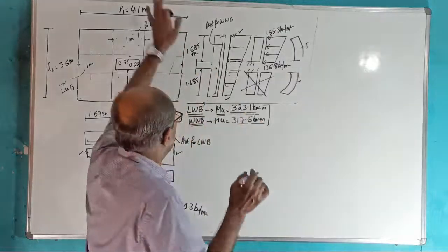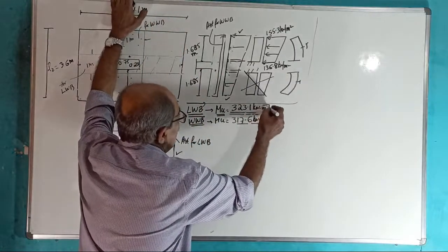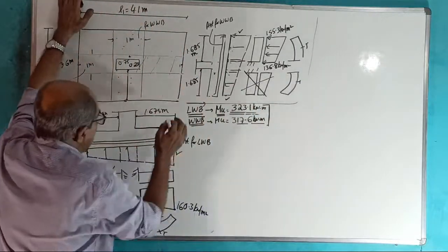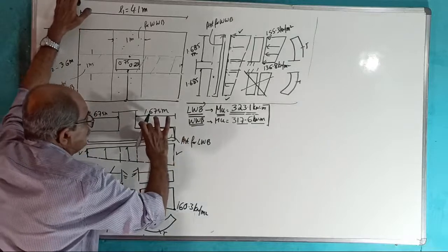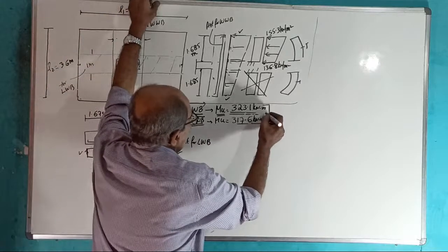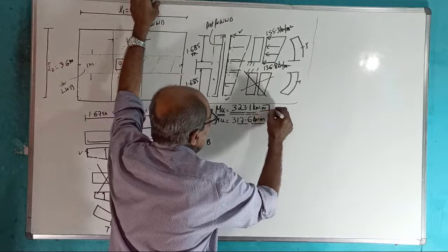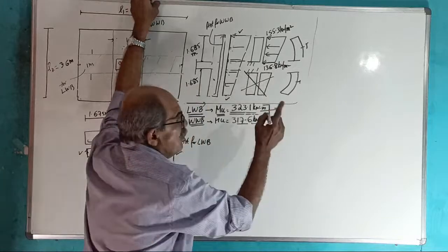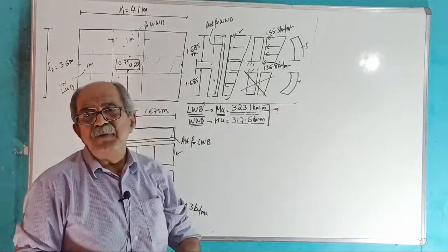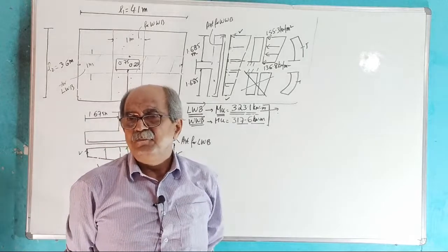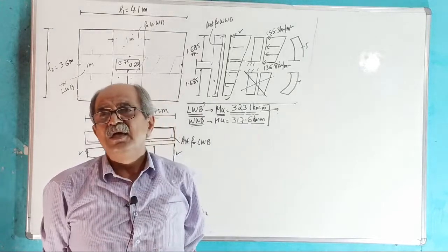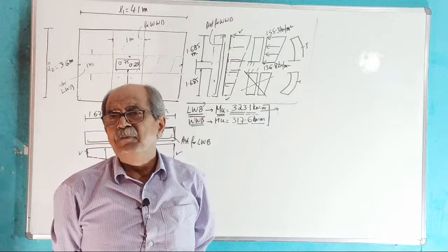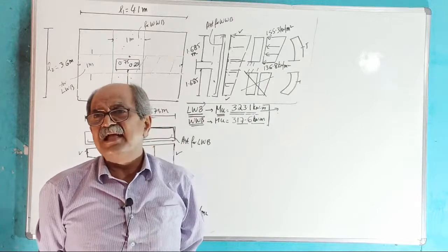Okay, leave it now. Now, you found these two bending moments, then we decided the depth of the footing slab. See, we considered the higher bending moment and found the effective depth required for bending moment, equating factored MU to MU limit, then adding cover, etc.